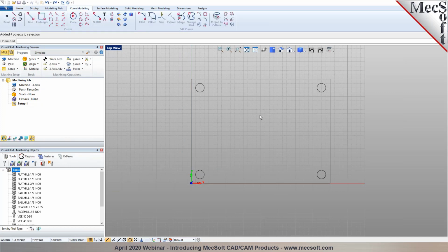I will go ahead and create a cutout in here by adding a rounded rectangle. We'll specify a radius. And I'm going to use some trim commands to trim these 2 out. I have automatic continuous recall on, so the trim command stays active. And the next step, I'm going to apply some fillets in here.